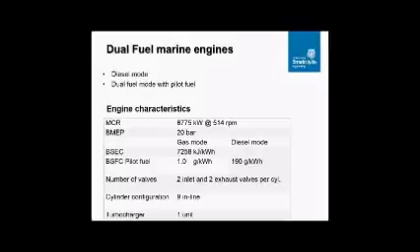Diesel fuel auto-ignites and creates ignition sources for the surrounding air-gaseous fuel mixture. The pilot liquid fuel injected by the conventional diesel injection system contributes only a small fraction of the engine power output. After the working phase, the exhaust gas valves open and the cylinder is emptied of exhaust gases.